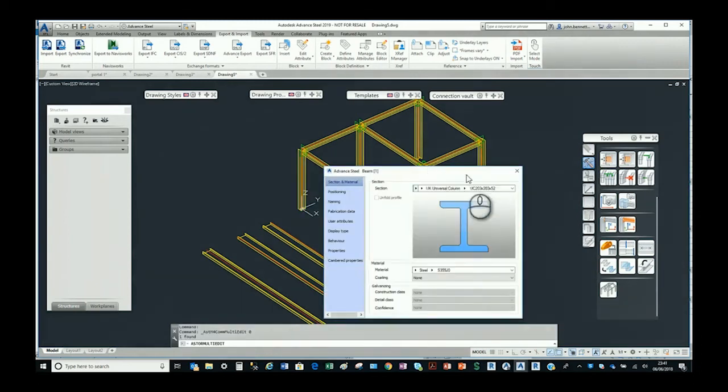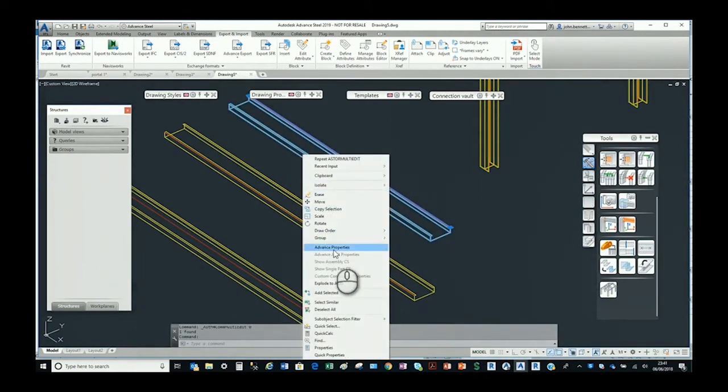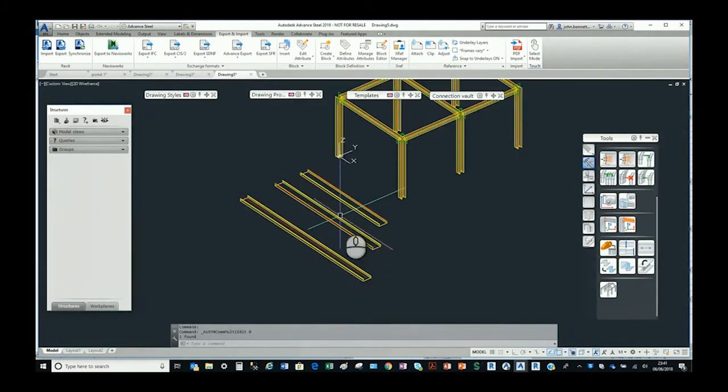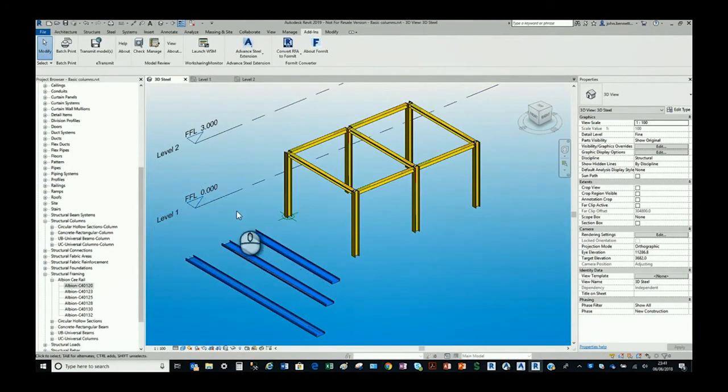And then if I just go down and check the materials variously throughout the model, you'll see that the columns here, the sizes come from the JO material there. This is now a dynamic profile, so it should only have one section listed under the drop down here, because it's dynamic, but the material does say cold rolled steel, so it came straight across. So just try and watch out for materials. It can cause a little bit of trouble. It seems a small thing, but it just can make life a little bit easier for everyone.